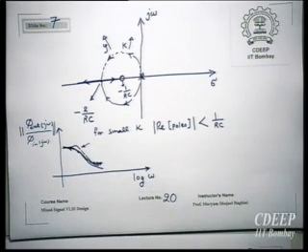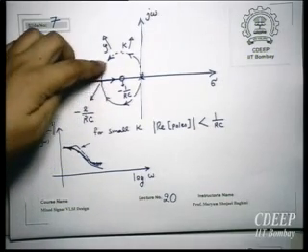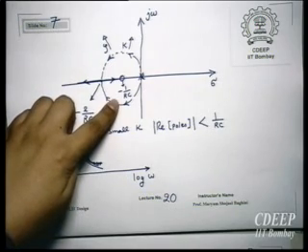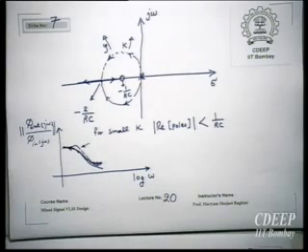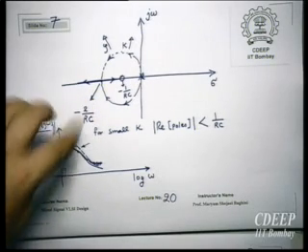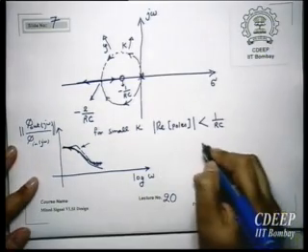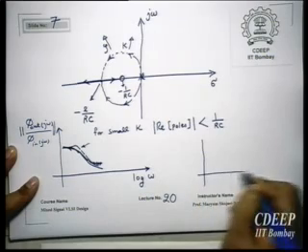Now if we increase k, it means that the poles will come to the left side of minus 1 upon RC, and still they are imaginary. Then this peaking will reduce, but now the 0's effect will come into the picture because now the 0 will appear first.